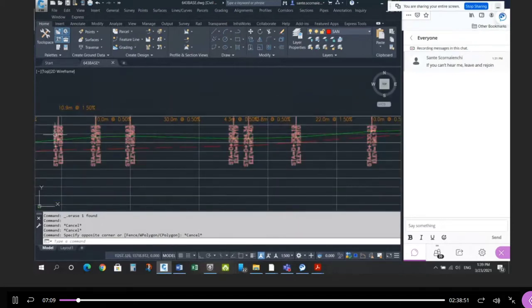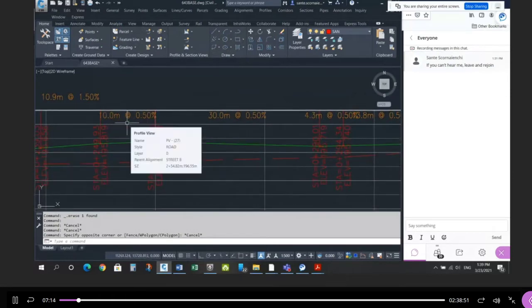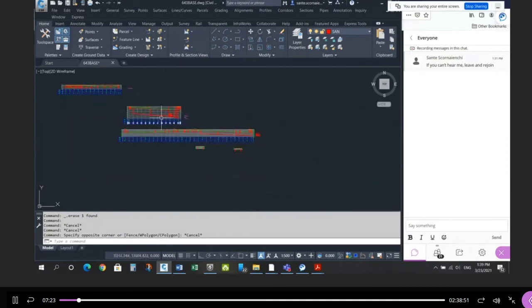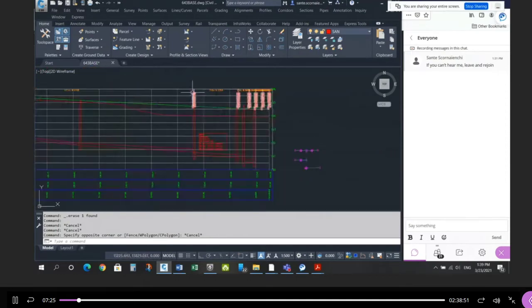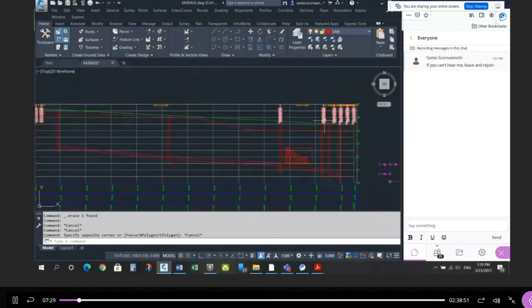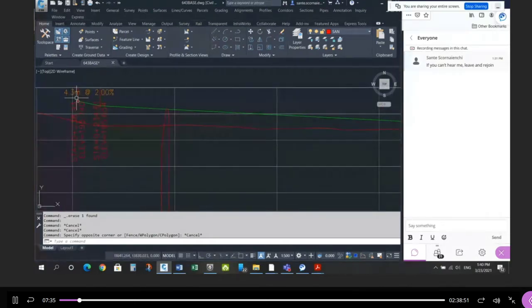And then coming up and up from both sides with this intermediate 10-meter long 0.5% grade, so that we don't have any A value or change in slope that's greater than 1%. Okay, so I looked at that. And then on street A, it was a lot cleaner, I think, a little easier to handle. Down 2%, down 0.5%, up at 0.5%, and then continuing up at 0.5% till we get to the edge of pavement here, and then up at 2%.